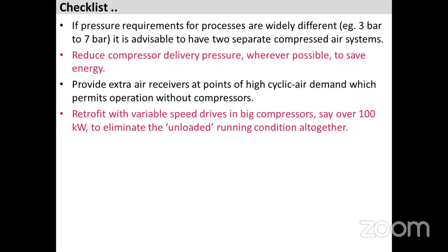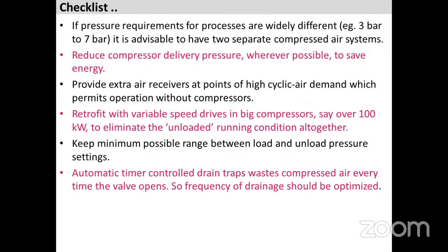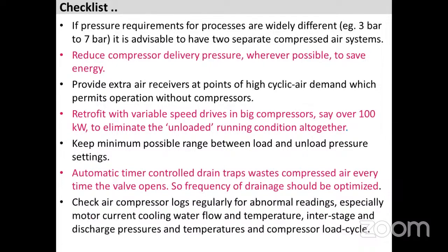Retrofit with variable speed drives. Keep minimum possible range between load and unload pressure settings. Automatic timer to drain traps, already you told, sir. Check air compressor logs, logging of readings, timing and all, that has to be checked.